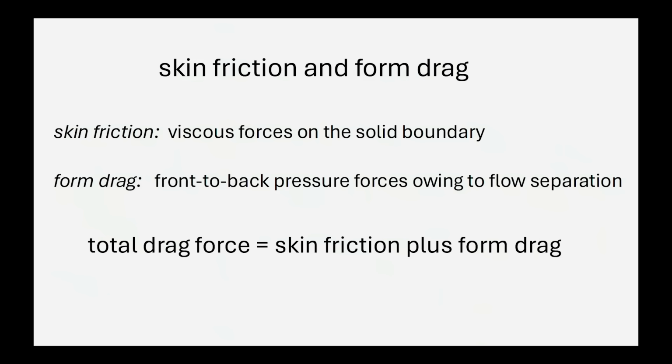I want to introduce two terms here: skin friction and form drag. I used the term form drag in an earlier figure, and I didn't think to define it for you. Skin friction is the viscous forces on a solid boundary, and I've told you about viscosity. Form drag is the front and back pressure forces because of flow separation.